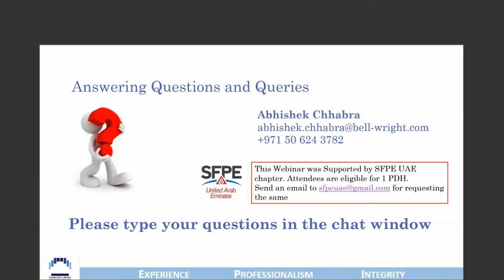And hence, if a certain piece of hardware has been certified and listed, which means that just like the manufacturing location of the fire door supplier is being audited to ensure that the quality is being maintained, it is relatively easy to swap and change the listing as against using a second hardware which may not have been listed or may not be under an audit regime of a certification body.